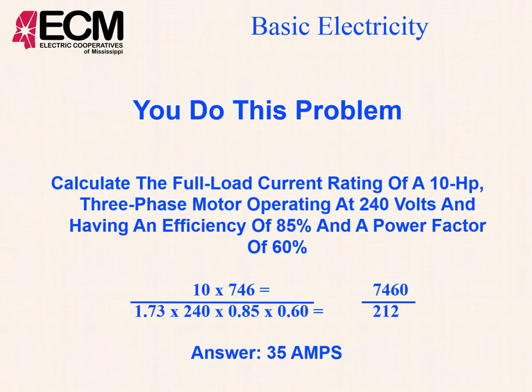So you would need wire big enough to carry 35 amps, and you would need a breaker for that wire to protect it at 35 amps.